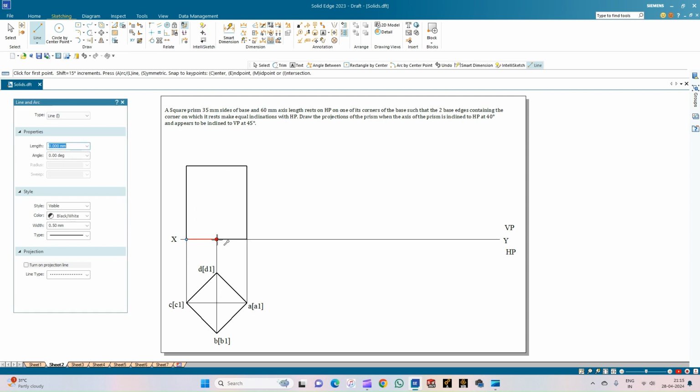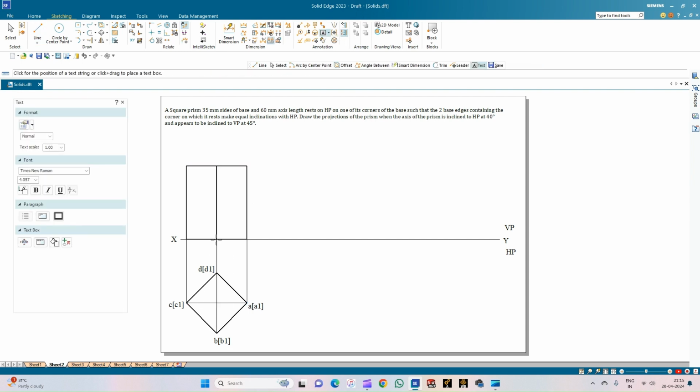And similarly, though there is an axis line, the corner line of this particular square prism, that is B1 D1, will be superimposed on the axis line, that is OO1. So that is the reason why this line is darkened and a separate axis line is not shown in the illustration of the front view of the square prism. And this is O and O1, that is the axis, the center point of the square polygon in the top and the bottom faces respectively.